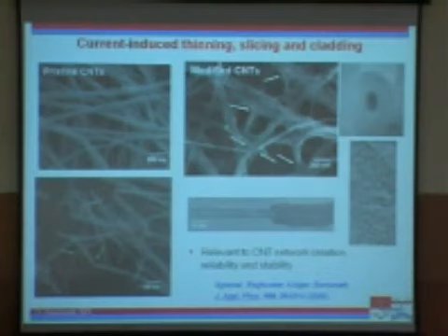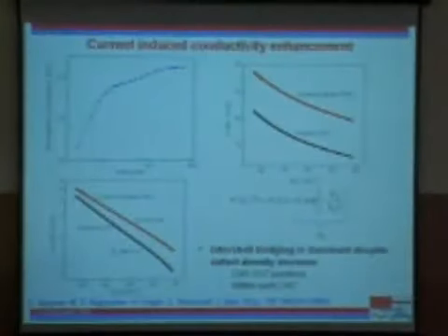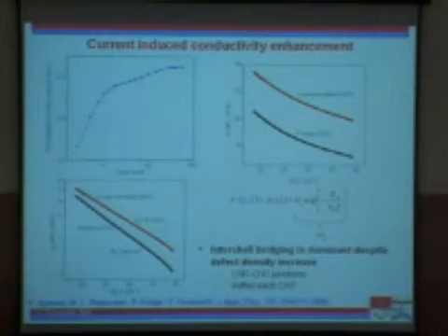And this you can do, of course, in a very cheap way. The very interesting thing here, though, is once you have these mats of nanotubes and you're passing high currents and creating sparks and breaking nanotubes, you would expect that the conductance will go down. Correct? But what happens initially is the conductance goes up in short time frames. The reason is, even as you're creating defects, you're also creating more pathways for the current to be carried through in this network.